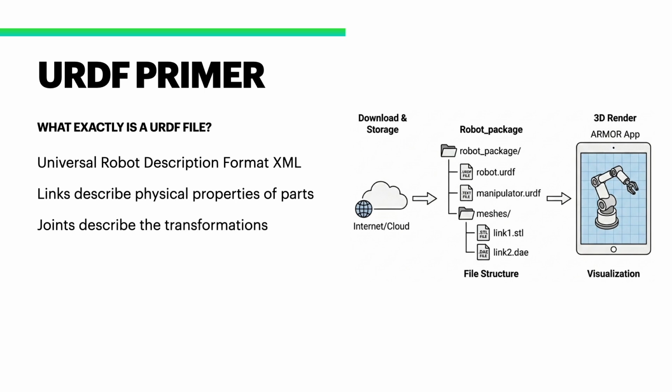Joints define the rotational and translational relationships between links, their degrees of freedom, and their constraints. Common joints include free motion, where a robot's base link is given unconstrained motion in all axes, and revolute and prismatic joints, where a link is given a single rotational or translational degree of freedom relative to its parent link.